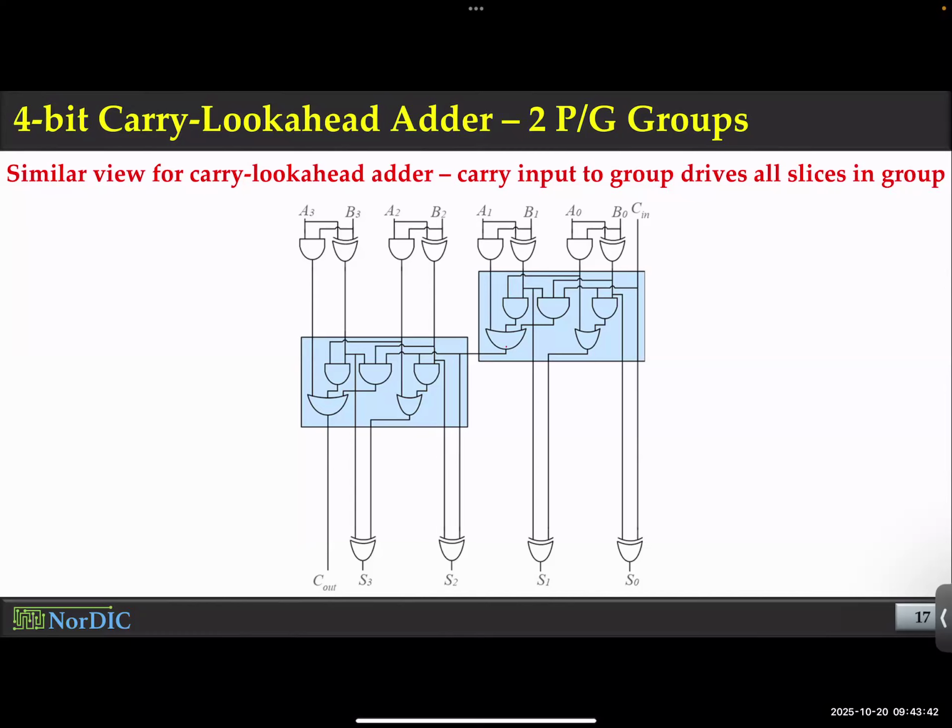Okay, so the concluding remark is you provide the carry output from one block to the next block as if that is the new carry in. So this is your new carry in for the next block. So this bluish zone is the CLA, carry look ahead logic. And then this is again carry look ahead logic. And there will be carry look ahead logics in every stage. So you could use this 2-bit look ahead logic and use it as a Lego block. Or you could do 4-bit look ahead logic, use it as a Lego block. I've even seen 8-bit look ahead logic. It makes sense in some cases, and you go through the chain that way.